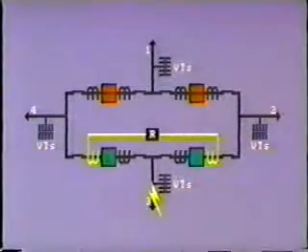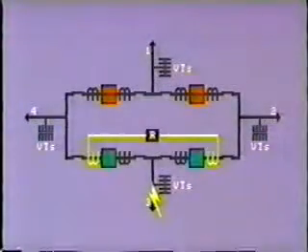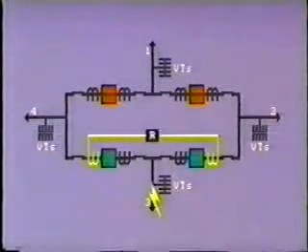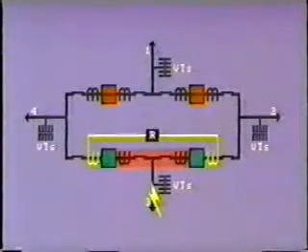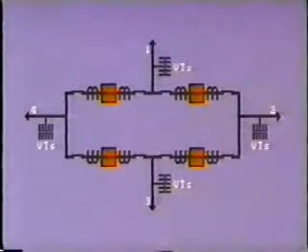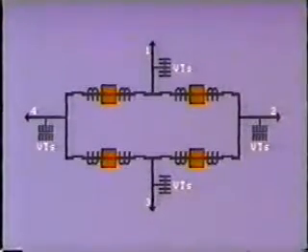For line protection, the CTs at either breaker must be connected in parallel, like this. This also provides protection for this section of the bus. Voltage for protection must be provided from VTs on each line or each section of the bus. With this arrangement, special bus protection is not required.